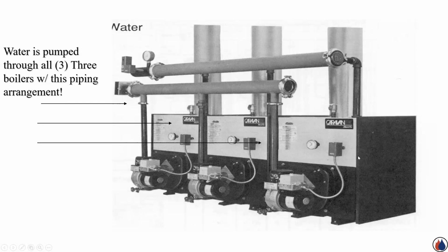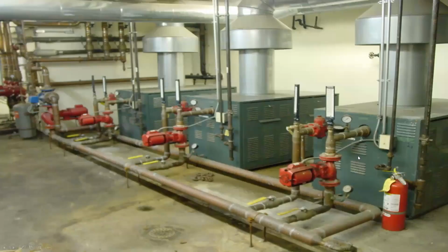40 years ago, 30 years ago, pretty popular. 50 years ago, popular. Because going from this one big boiler to these 3 smaller, I look at the fuel savings, and there was some, but they were missing some. So then they go to these multiple boilers, and they decouple them, and they have the closely spaced T's, and they have the boiler pumps on each boiler. And in this case here, maybe they're non-condensing. So you got to protect the heat exchanger and the breaching, the flue vent piping. So then they introduce some type of mixing valve to take it even a step further. So I get 2 or 3 boilers, then a mixing valve going out to the building.